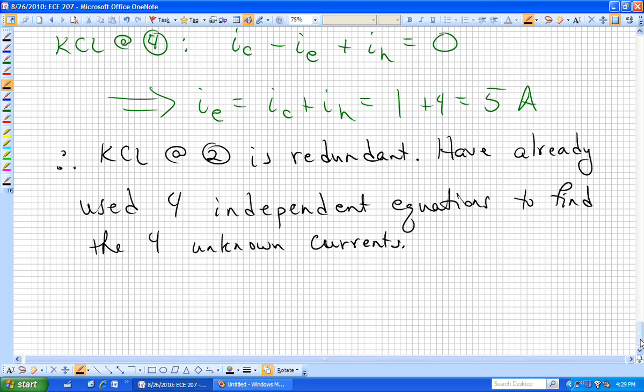Meaning if you find I sub A to be minus 3, I sub A is always minus 3. You can't say I sub A is now 3. Well, you said in or out is plus or minus. I hope that's not what I'm saying. I'm saying that the sign is whatever you want it to be. If I now establish a convention that in is positive, then if I sub A is going in, it would be positive in that particular writing of the equation.